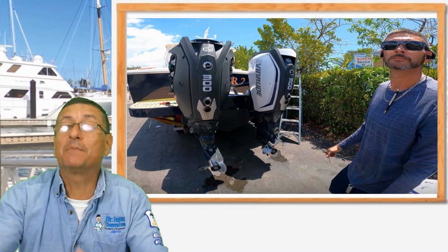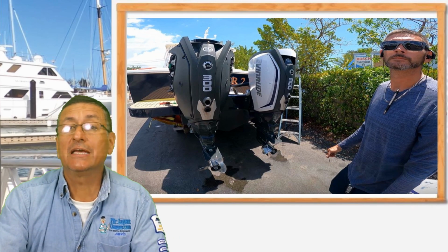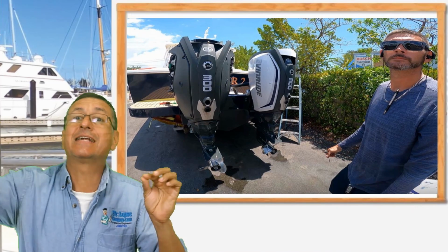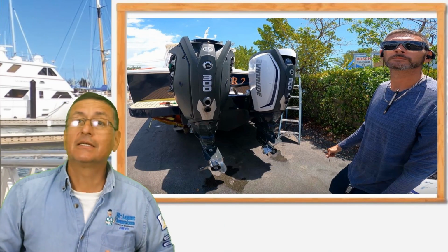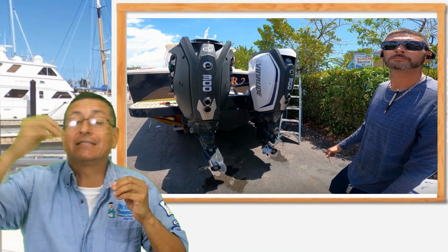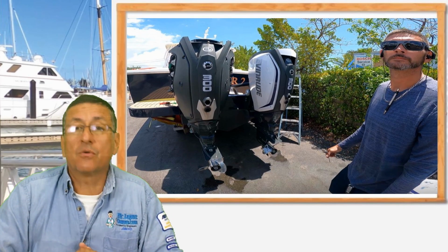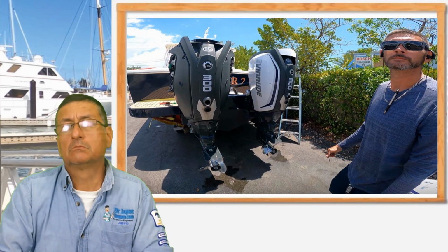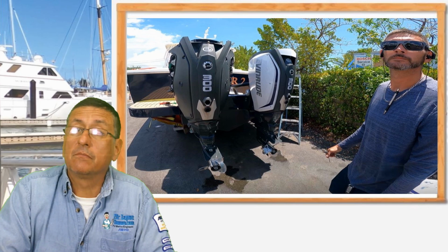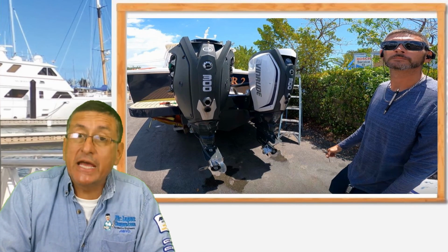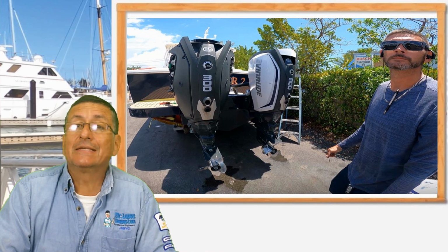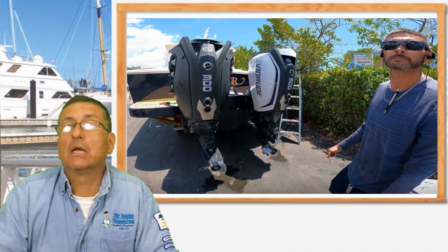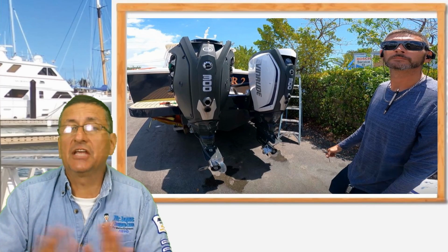Yes, in this particular case, the solution is to replace the module because the sensors are good, the sender is in good condition, the harness, the relays are in great condition, the source of power is good, the ground is good. The only possibility, according to the help desk and the manual, is to replace the module. They ordered the module, they replaced the module, and the engine starts perfectly.